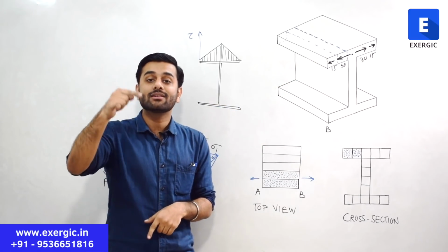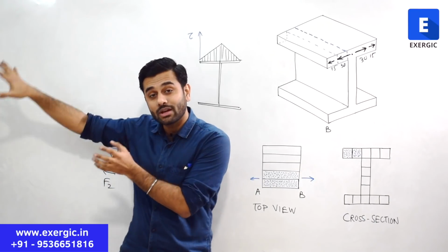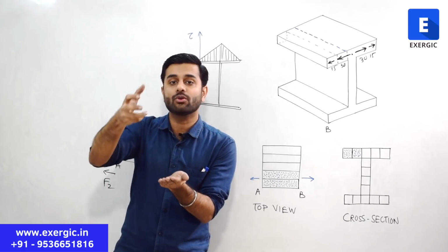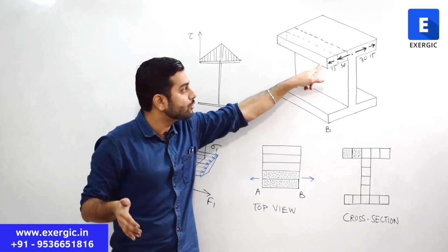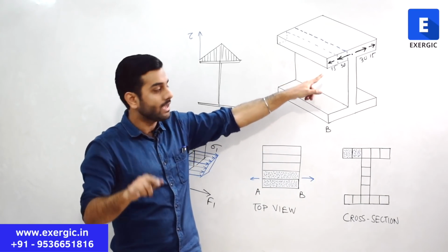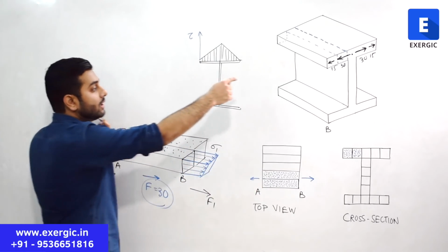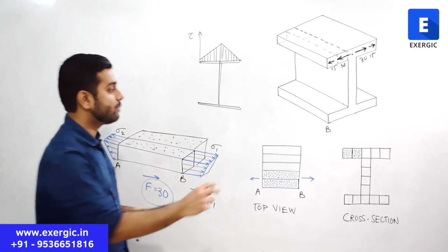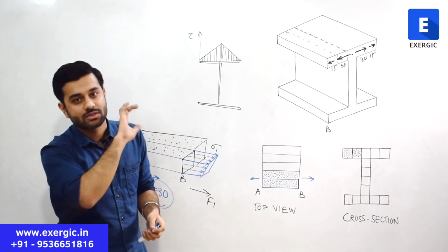Just like the value of shear stress was 0 at the top surface. If you recall the shear stress in beams, on the top and bottom surfaces it was 0 due to the same reason. So for the right and left portions, it is going to be 0, and it is going to vary linearly like this. The same thing is going to happen in this bottom part also. If you start analyzing this bottom part, the same thing will occur, but there will be one small change.